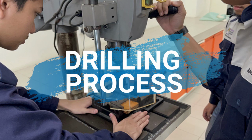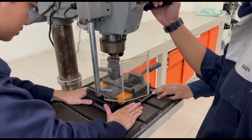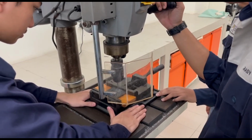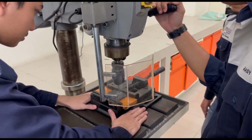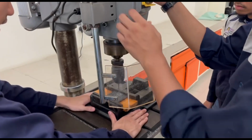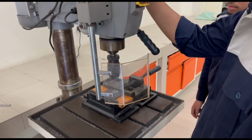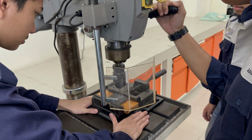For both of the steel plates, we drill 4 holes. We used a 3 mm diameter drill bit for the drilling process. We mount the drill bit and steel plates on the bench drill. Then we proceed to drill the steel plates with caution to avoid injuries and errors, locking the steel plates in place.